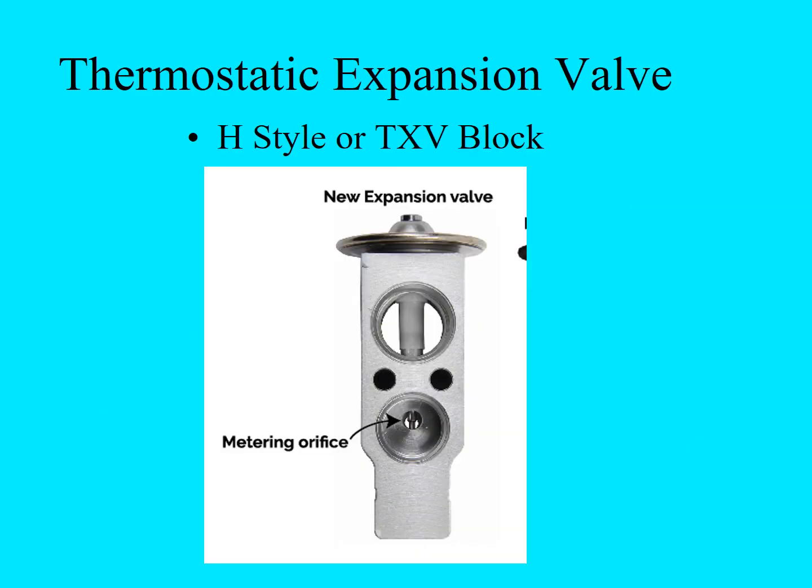So this is showing the TXV block style valve, and this has become very, very popular because it makes a very easy connection for the high and low side lines going to the evaporator. At the bottom portion, this would be the high pressure side coming into the valve, and you can see in the back is the metering orifice.